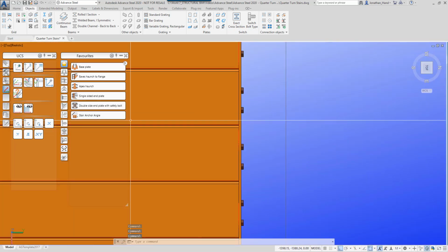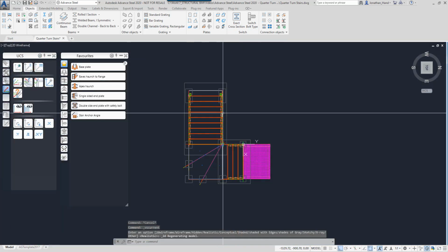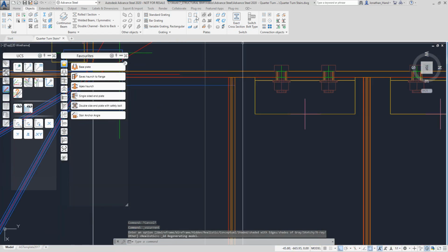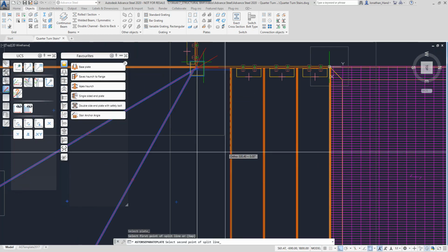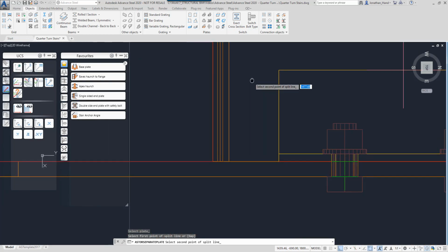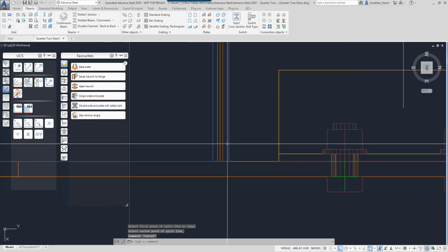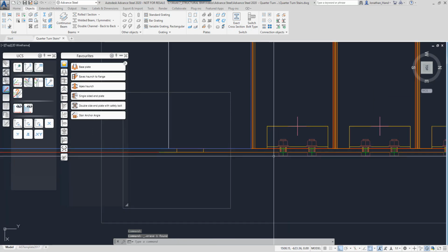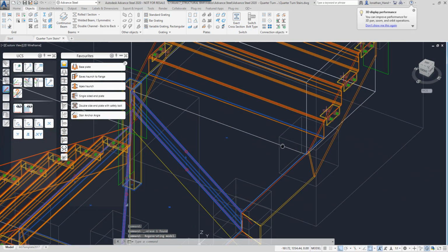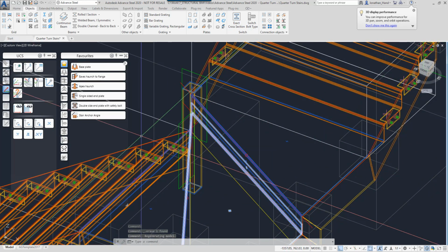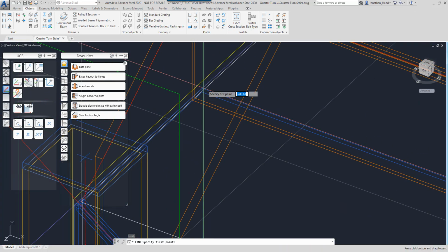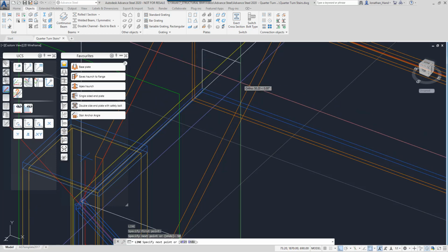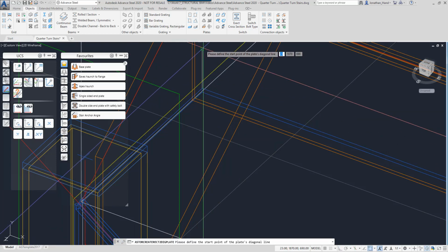We can just go down on top again, and we just want to split this plate along that front point just there, and then I can remove that section, and we have a quick orbit around, and you'll see that's what we get. So if we also just rotate the UCS, I can draw my plate here, and I'm going to put a little lip up of, let's say, 50 millimeters, and then I can draw a 2-point plate from there.